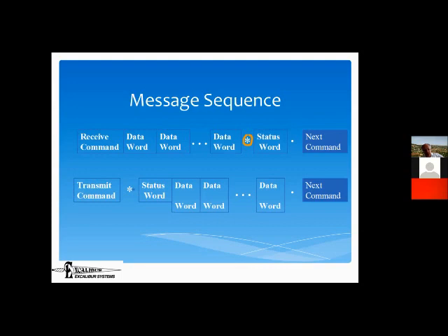The bus controller at some point has to know to give up, that he's never getting a response. Otherwise, he's going to waste too much time waiting for it. And therefore, the spec says, and this is an order of magnitude of about 10 microseconds, that the status word is supposed to be sent back. And if the bus controller doesn't see a status word in the course of, let's say, 14 microseconds, then he's going to give up, and he's now allowed to send the next command.